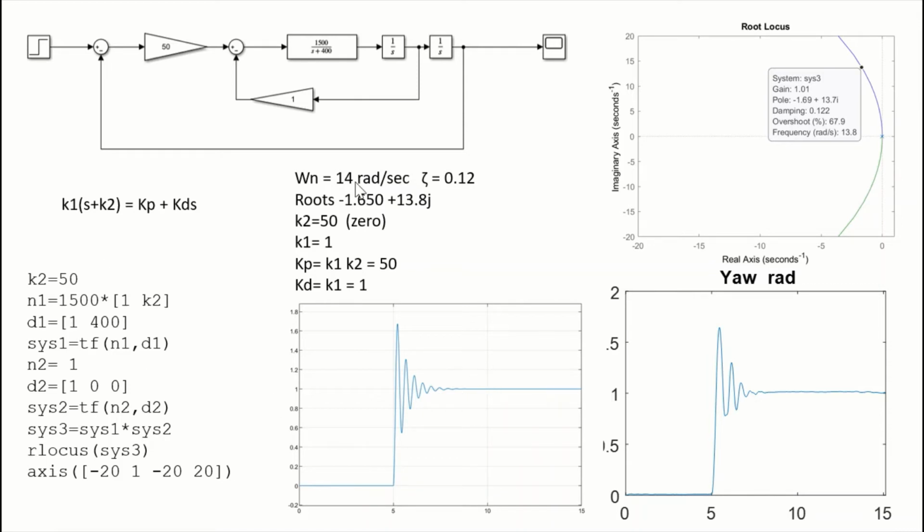Here's the code for plotting this root loci. And then we put these numbers out to the real drone, and here's the drone response. We can see now there's a very good correlation in terms of damping ratio, overshoots and undershoots, between the simulation and the real response. Whilst this flew, although it yaws very beautifully, it generates a lot of interaction on X and Y in particular.